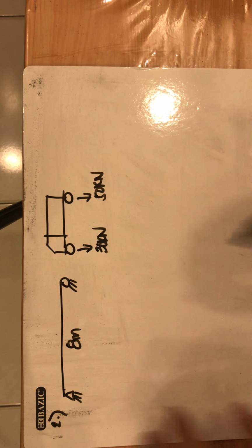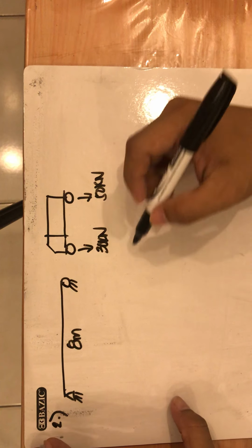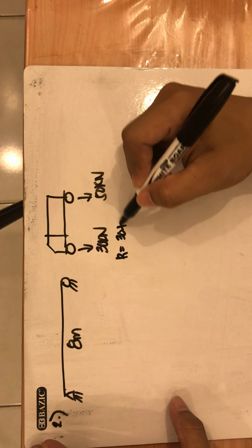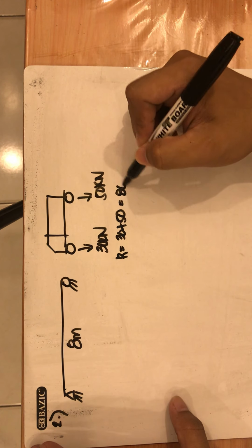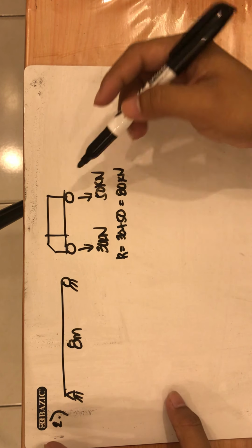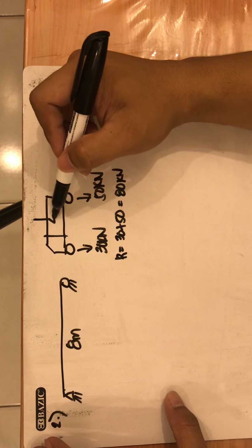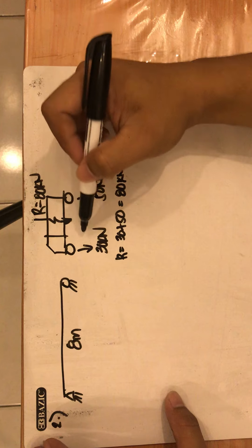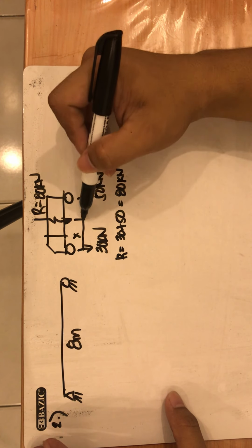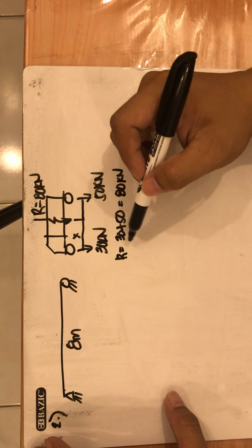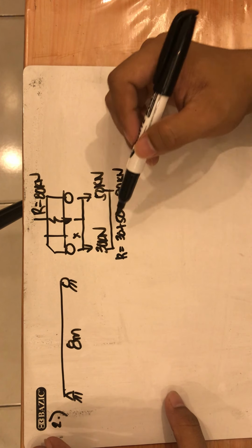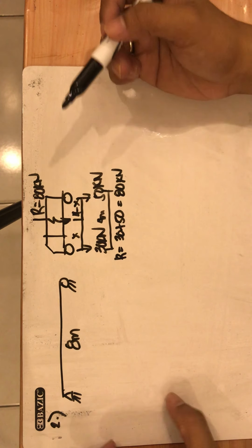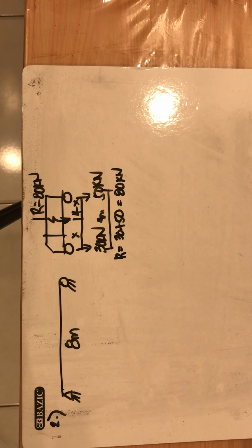So, we determine the maximum moment and maximum shear. First step, right? Determine first the resultant. Resultant is 30 plus 50, equivalent to 80 kilonewtons. Then next, determine the distance of the resultant from the front and rear axle. I'll call this X. Then the other one, the total distance between axles is 4 meters, so the other is 4 minus X. Same procedures.